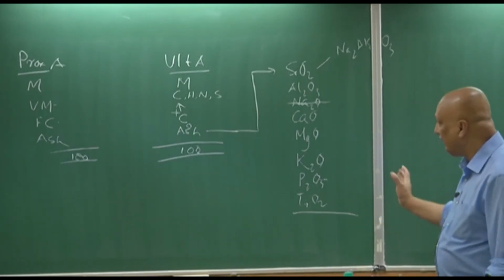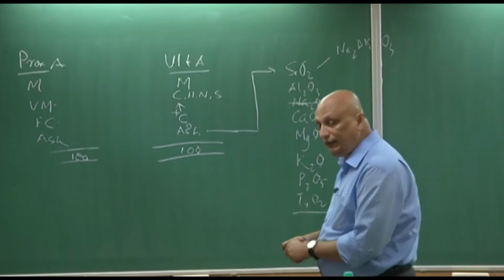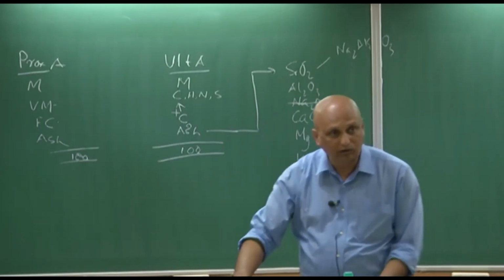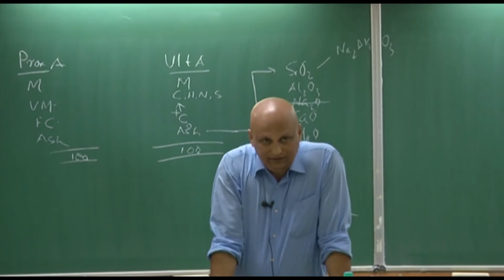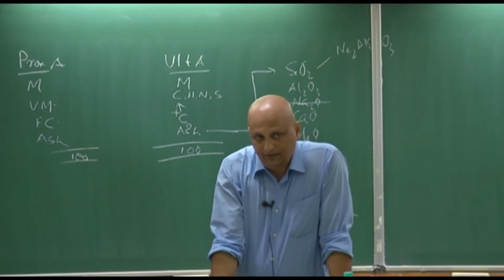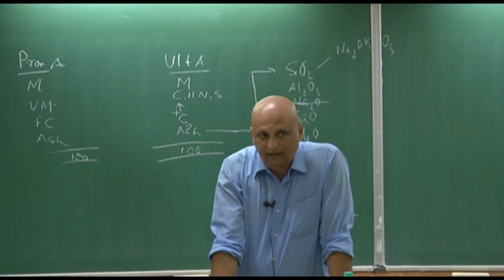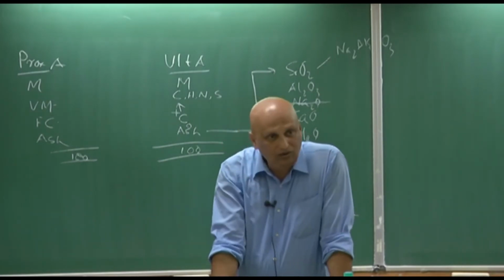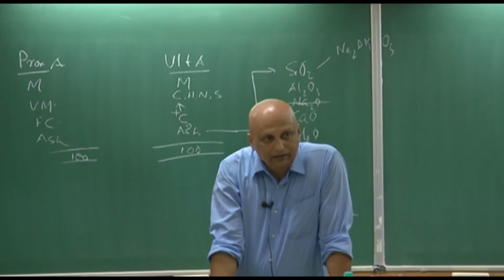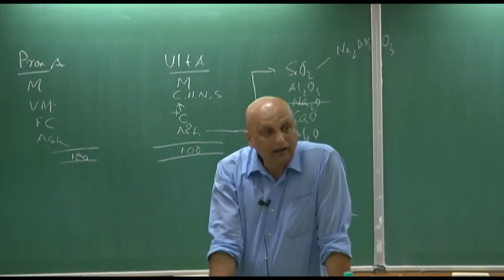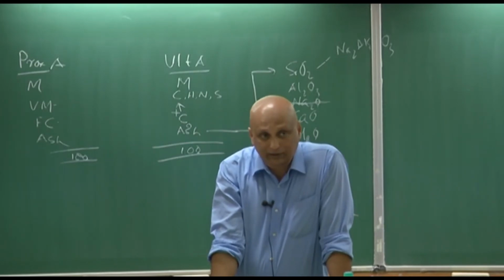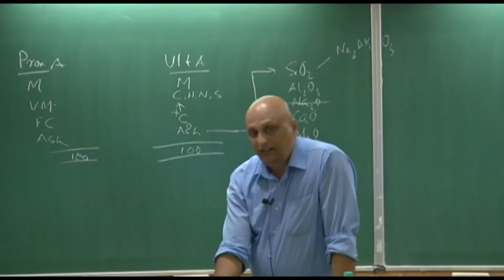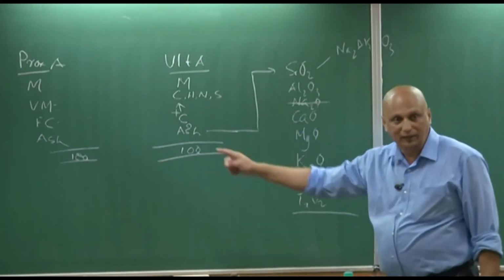So these three together are extremely important for the boiler manufacturers to give you the design of a boiler. They calculate the boiler size, the near burnout zone, how long that should be, the actual burnout zone, how long that should be, what should be the volume, what should be the residence time there. They design it as soon as you give them this bit.